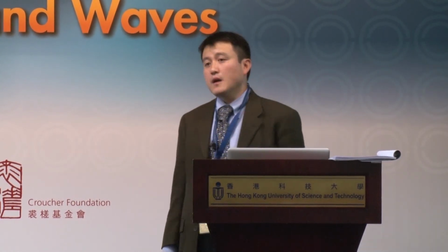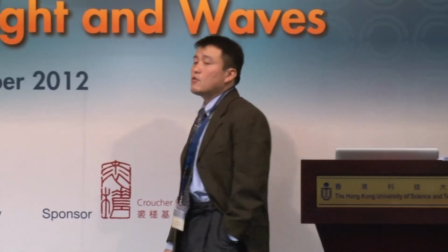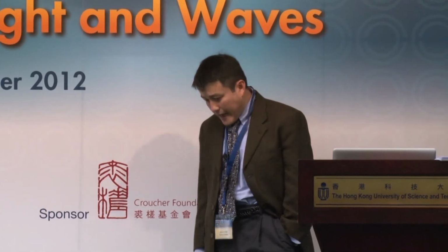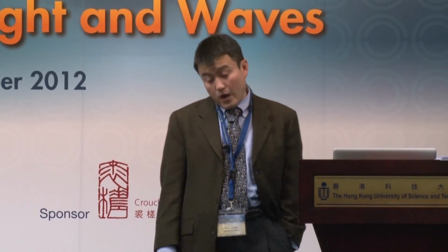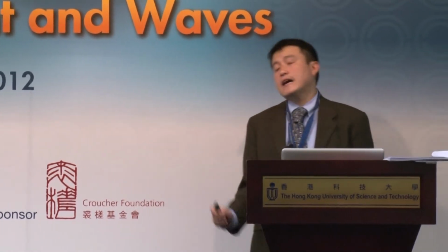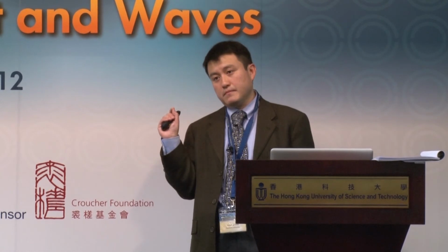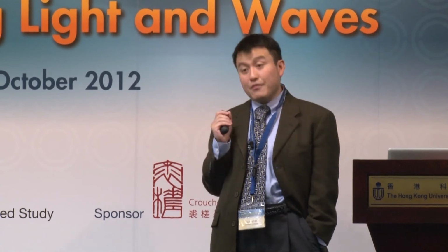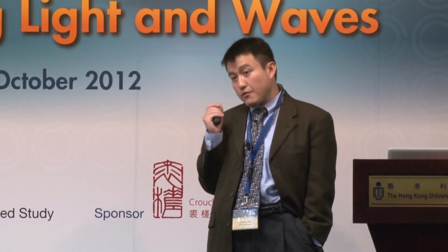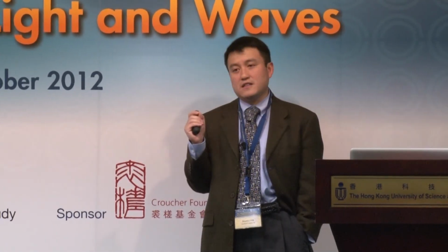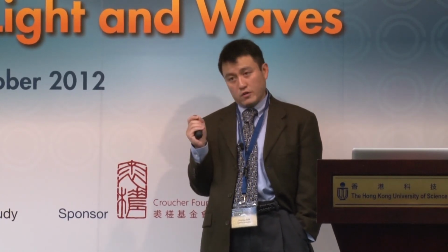If you look at their data, their isolation region, first of all, they did a ring resonator, which has very small bandwidths. And the second point, which is more fundamental, and they showed that as well in their paper, is that there's only a range of intensity where you show isolation. That fundamentally says that you have to assume something about reflection. Now, the point about isolation is to assume that the reflection is unknown, and you want to get rid of it. I think that's a very important point. In fact, if you know something about reflection, you do not need an isolator. And that's almost universally true.